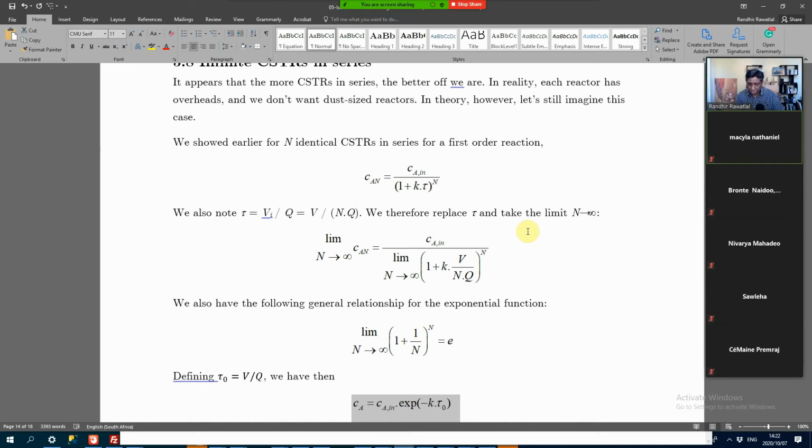However, you can limit your value of n. So it's not the case that n has to be 1 or infinity. You are free to choose, as the reactor designer, an intermediate value for n. So if you choose 2 or 3, you can see already you are getting volume improvements. So you are basically getting this in-between state. It's in between where you have perfect mixing and no change in time, and where you have perfect non-mixing. So you can balance between those extrema.